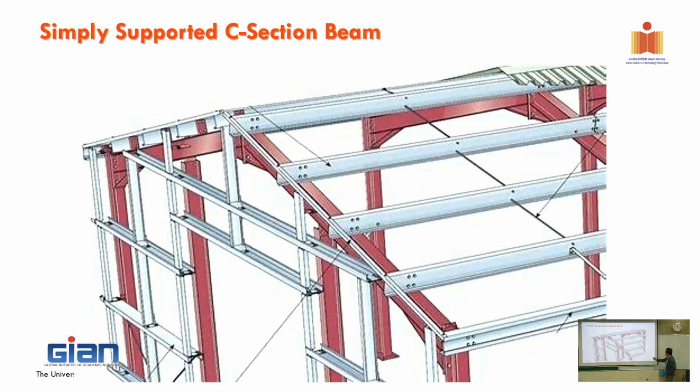So I take an example here where you design a purlin C-section in a roof system, and we assume that it is simply supported. And in here you have what we call in Australia row bridging. Saddle in here. Sag rod. Or sag rod. Okay, you use that one.